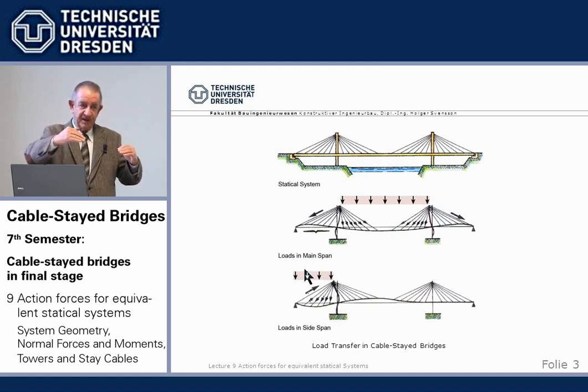So it becomes clear we need a certain minimum amount of forces in the backstay cable, so that if we get the compression from the side span loads, the slack of the backstay cable doesn't become too big. The effective E modulus must not be too low. But we understand we carry compression in the backstay cable by a reduction in the tensile forces from permanent loads.